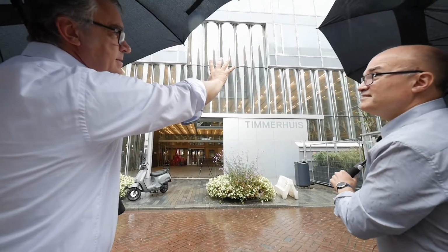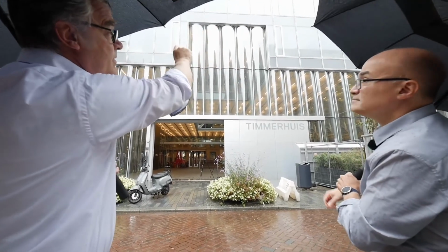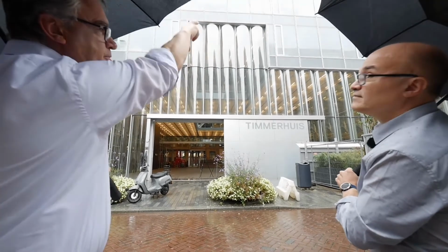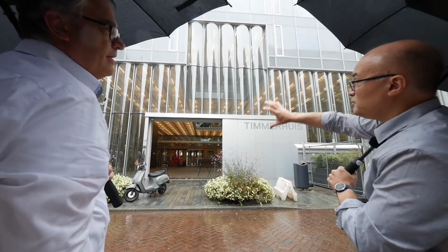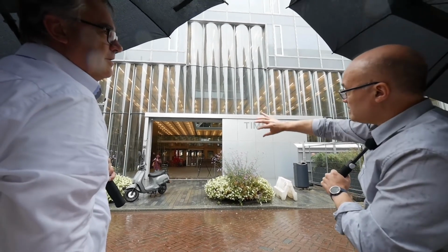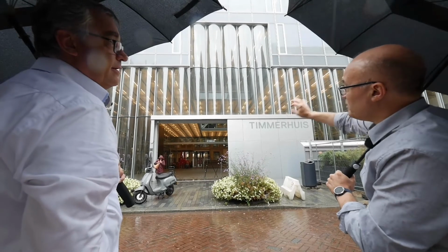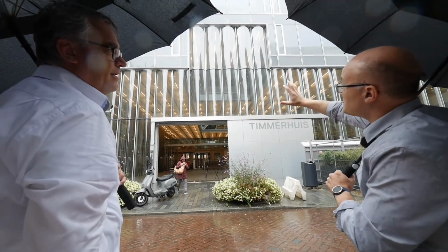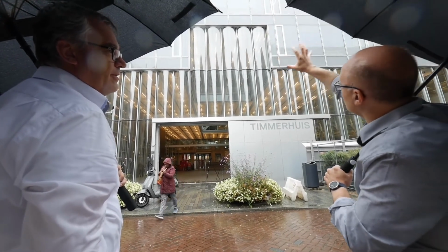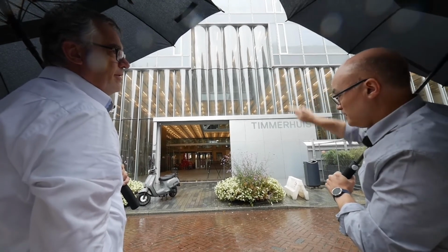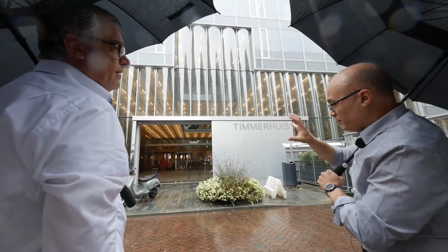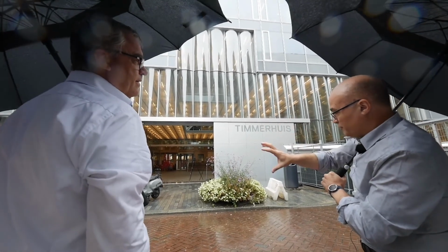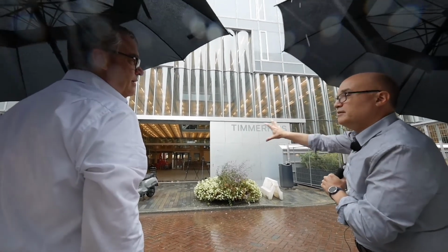As we discussed, there's a unitized system at the top, and they come as units which are hung in position. Yes, correct. So the bottom is built on site. All the elements, the glass, the mullions, the frame, are brought separately on site and built on site. And the top unitized system that you can see there comes as panels which are prefabricated in the factory, with the frame and the glazing units all installed in the factory, and brought as a panel and installed on the building.